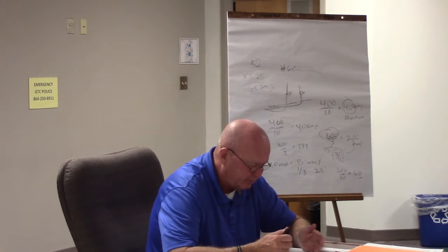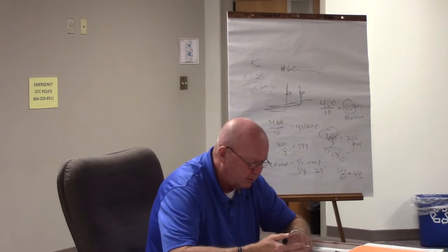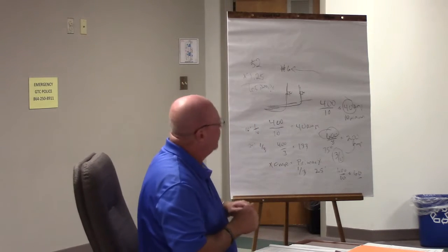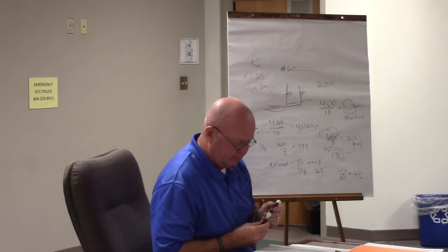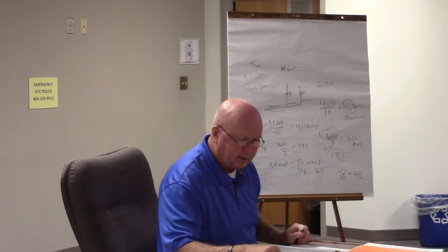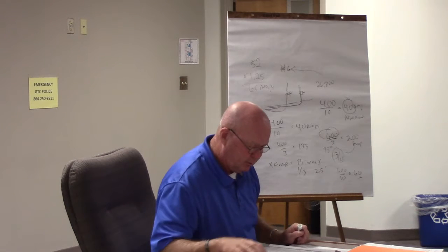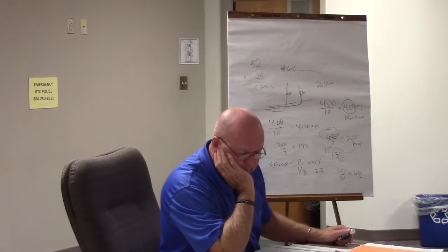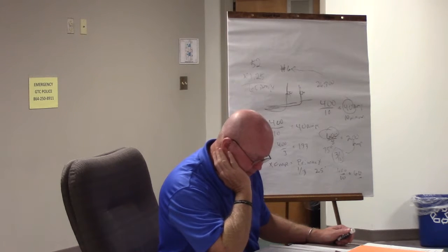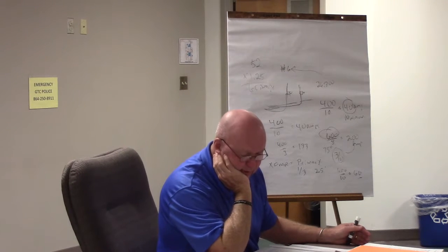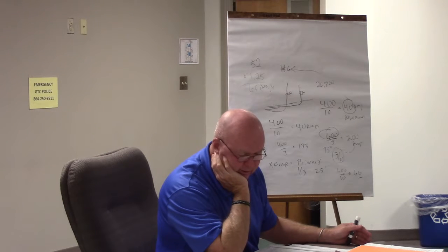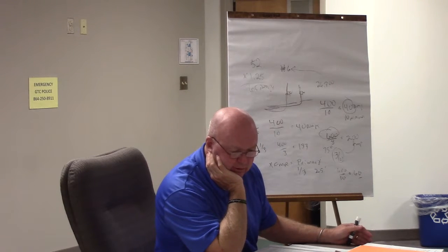All right, let's look at a couple of examples here. Example: the total general purpose receptacle load in an office building is 26,800 VA. What is VA? Okay. Let's go back to our lighting load, which was 220.42. 220.44, I'm sorry. Because we're not in a dwelling, are we? My bad, I went the wrong place. So it says receptacle loads calculated in accordance with 220.14 H and I shall be permitted to be made subject to demand factors given in 220.42 or 220.44.